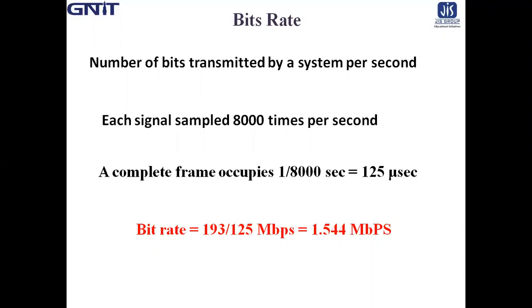So the bit rate is 193 by 125 Mbps, that is 1.544 megabits per second.